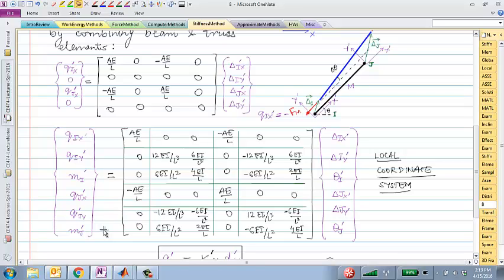But what we do need to do is what? Before, how would I use this local force and displacement relationship for a frame element? Right. We would need to transform this to global before I can add it to a different frame element.